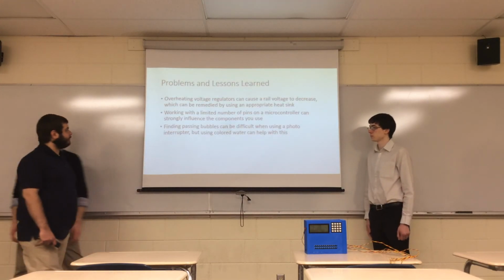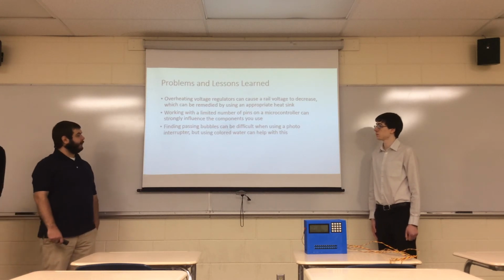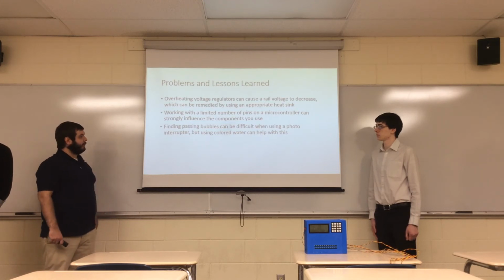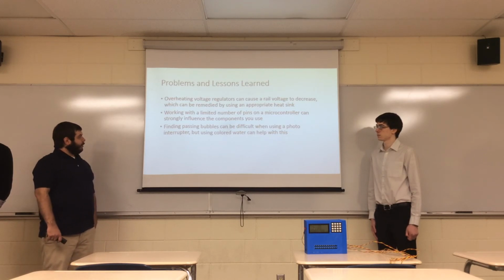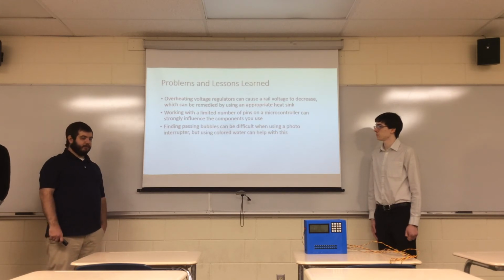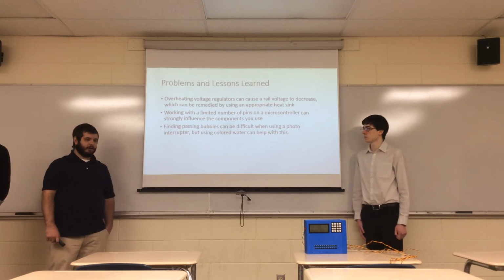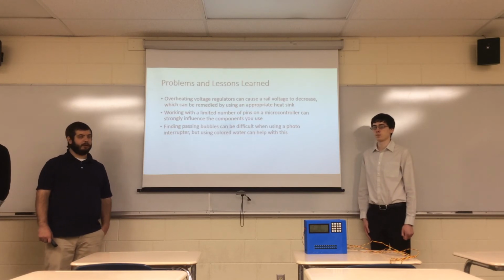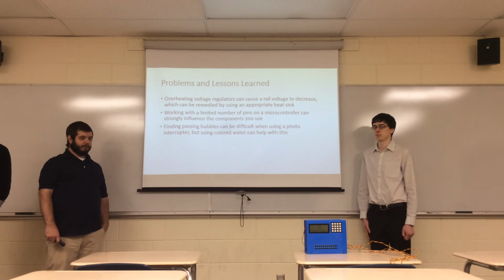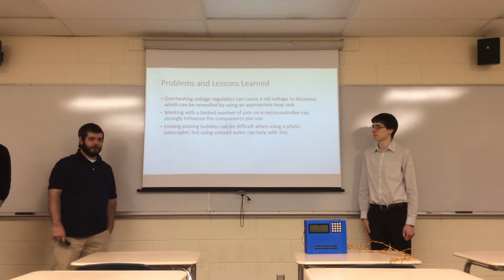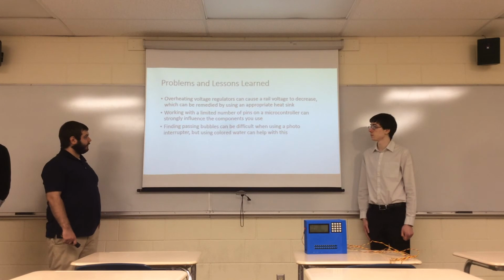Some problems and lessons learned is we had an overheating voltage regulator that caused our voltage rail to drop and caused issues with the screen. We ended up remedying by buying a heatsink. Working with the PIC, we had a limited number of pins, and this influenced some decisions like using the encoder, selecting a screen that could be used with the PIC, and eliminating some other functionality like separate buzzer and alert bar notifications.